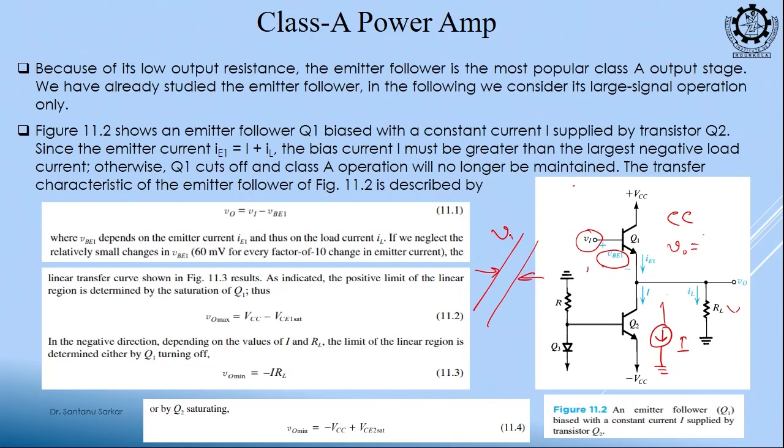So, this is your VI, this is your V0 and this gap is VB. Can you recall? So, input is VI, you subtract VB, you arrive at V0. So, you can tell that V0 is equal to Vi minus VB. So, you can also say this is having a DC shift.